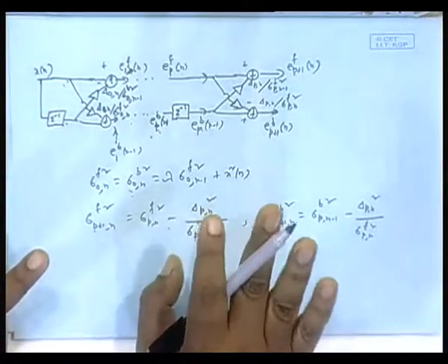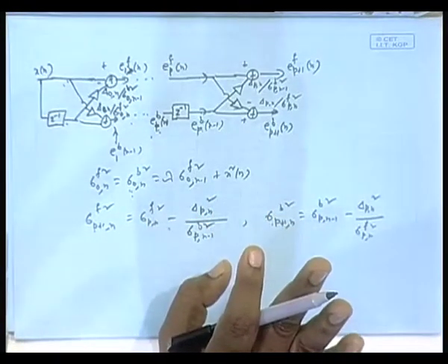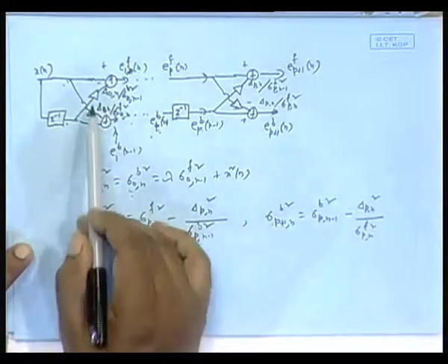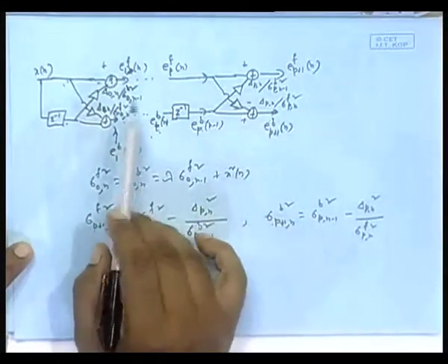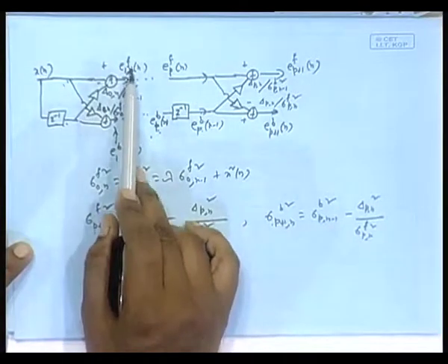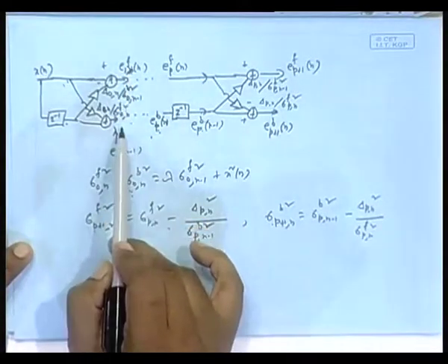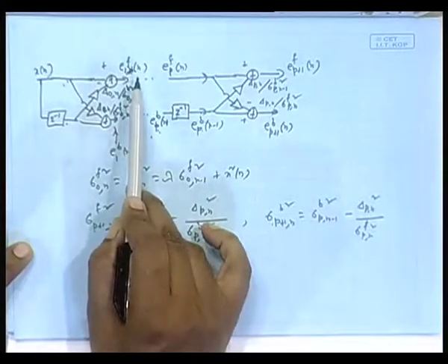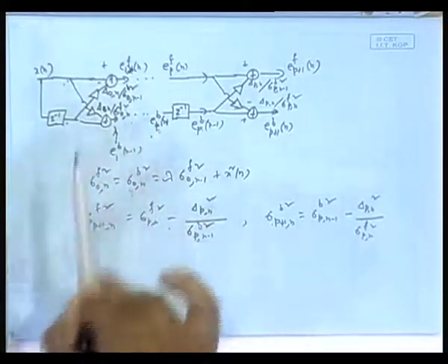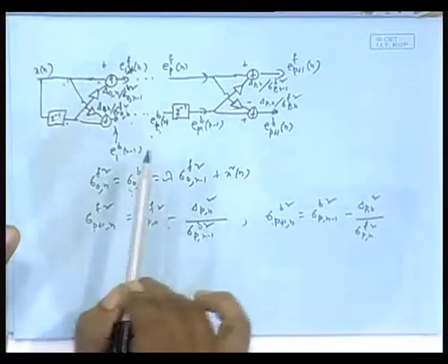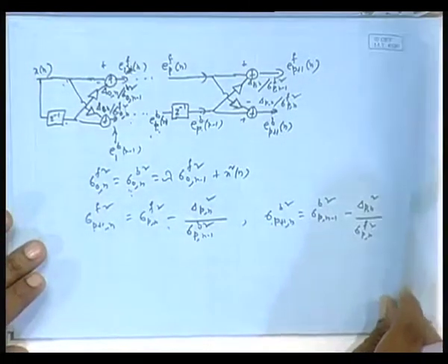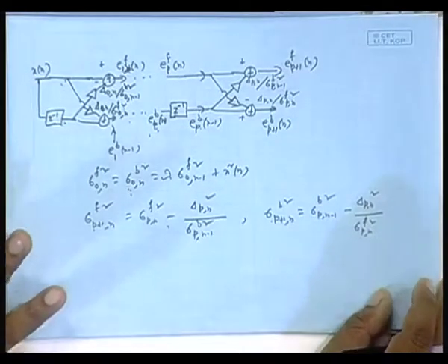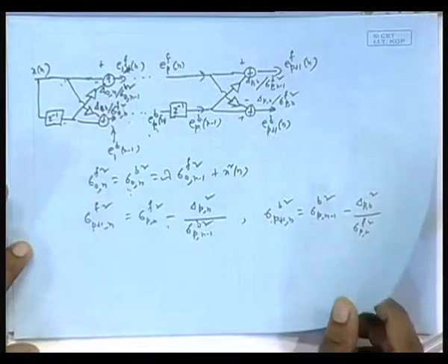You understood that adaptation phenomenon, isn't it? Because at each index n I am adapting the coefficients. Variances are updated order recursively and using the two prediction errors available with us and the past value of the delta for that particular stage. By some formula we will be calculating current value of delta. Okay. So now our main task remains as to how to compute the current value of, how to time update delta. Let us spend some time on that.